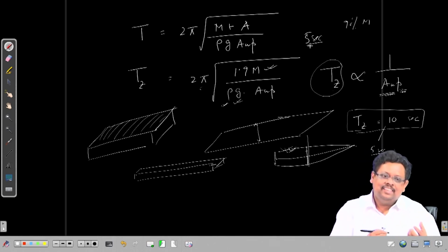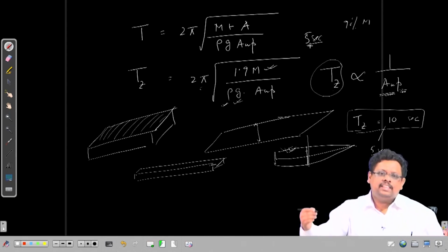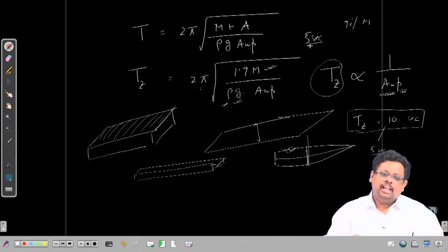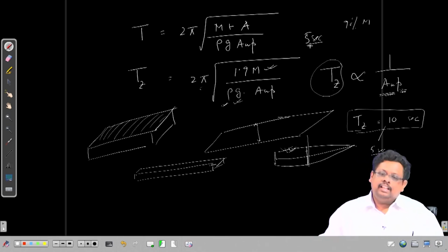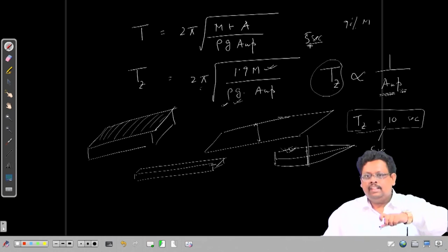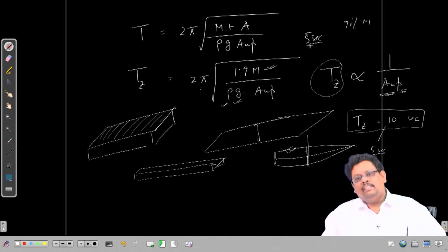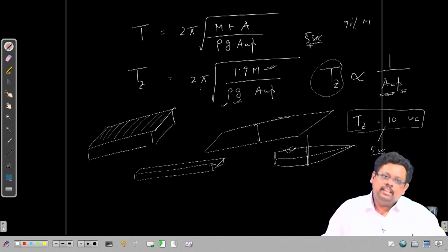On the other hand, if I try to make the ship very stable by increasing the beam, then because you have a limitation on the length, of course, you can't make it 300 or 400 meters long to increase the waterplane area, and that does not help either, because your momentum is not changed. So anyway, these are very interesting things, especially for engineers who are going to design a vessel, an inland vessel or something like this, with passengers, some ro-ro, sea-ro, pax ship. At that time they have to think in a very logical way about how to go about this.